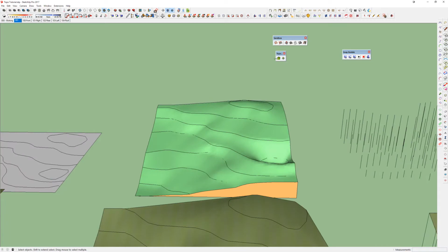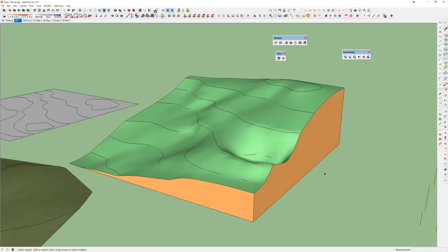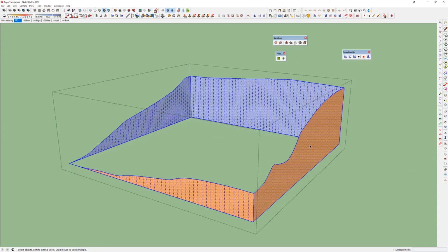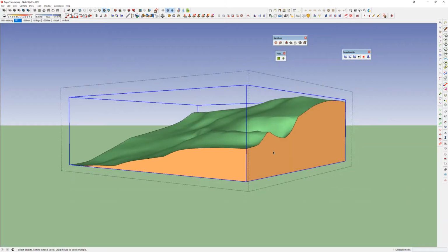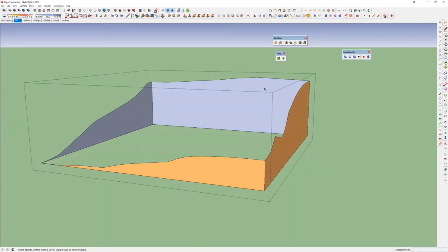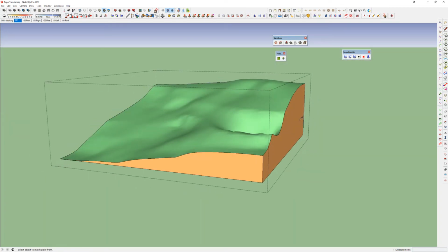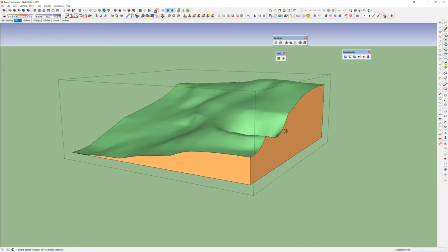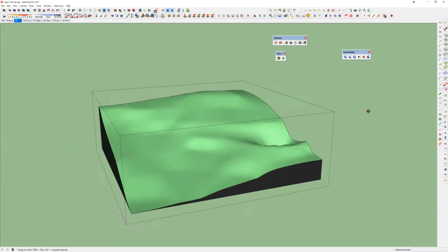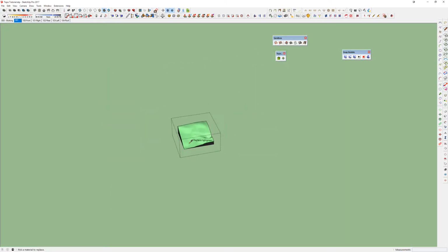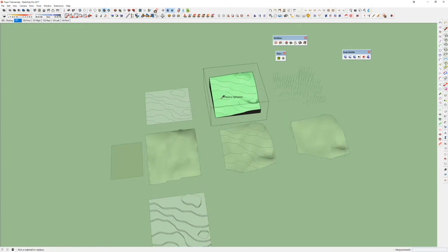And I'm pretty sure that when you run TopoShaper, you can specify what colors these things are. But it's nice because it does create almost a solid for you. I mean, they're their own group, so you'd have to explode them and make a solid, and it just paints them this color, so you can actually come in and paint it, say a black. And even using our material replacer that we talked about, I'm going to say replace this light green with grass.